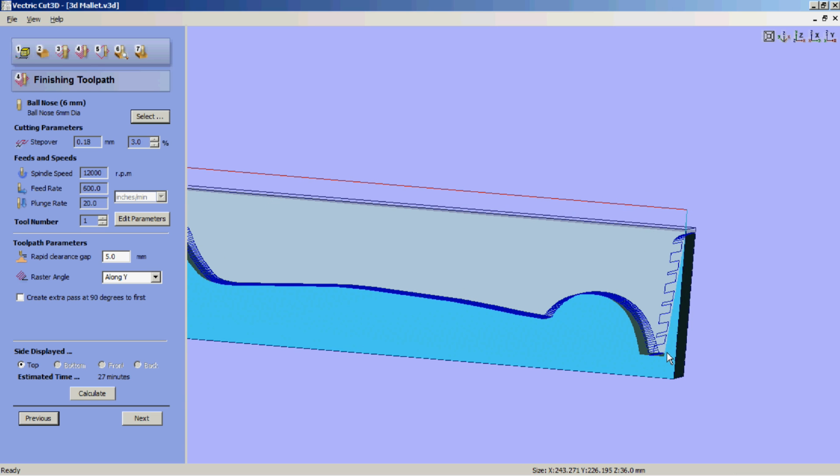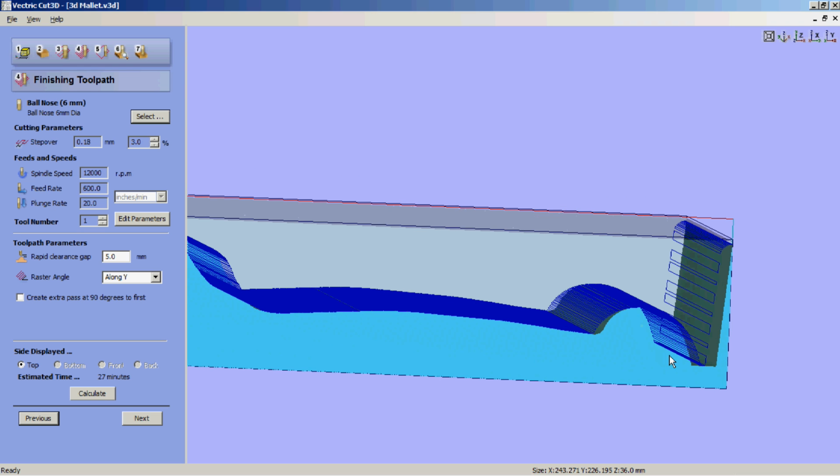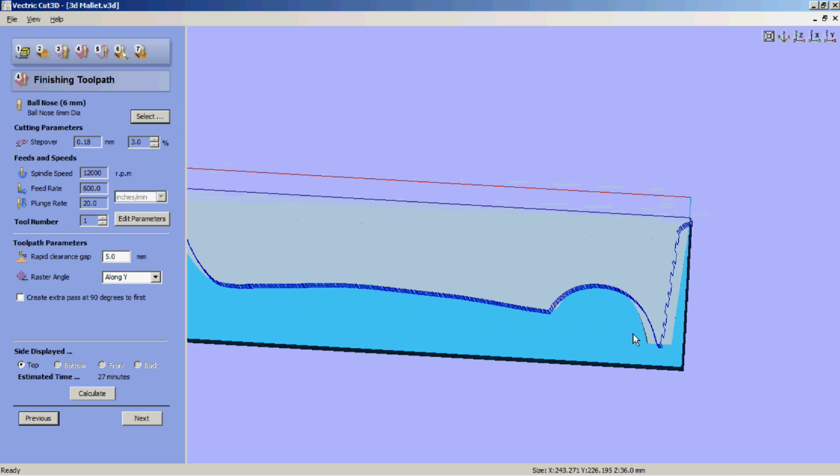Here's our holding tab, and here's the sloping path from the surface of our material down to the holding tab. You'll see the toolpath that's been created moves its way slowly, and then slowly starts working its way down this material until it reaches the bottom and starts machining this piece here. Now remember, I've left 1 millimeter of stock to be machined off in the final hit.